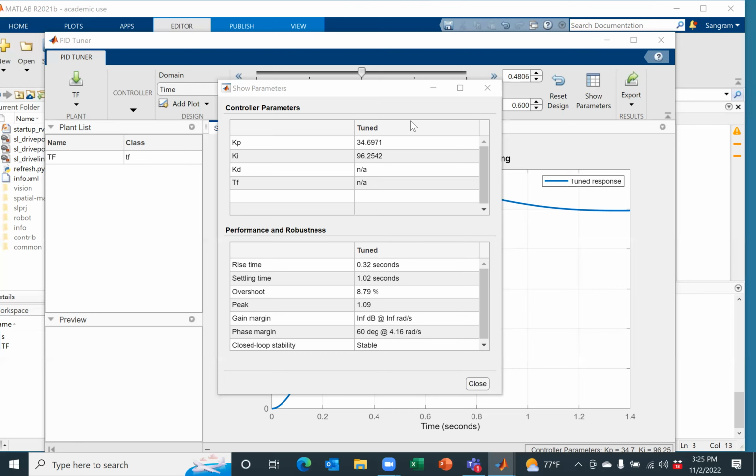I'll give you an example. You have a thermometer. You dip the thermometer in a pot of boiling water. There is some time constant before that mercury expands and reaches the steady state value. That time constant means the output is delayed with respect to the input. So think about it like this: if you were to feed a sinusoidal input, the output would be sinusoidal, but the output will be delayed. And that is what is meant by phase, the degree separation between the input and output. So that's why it is measured in degrees.